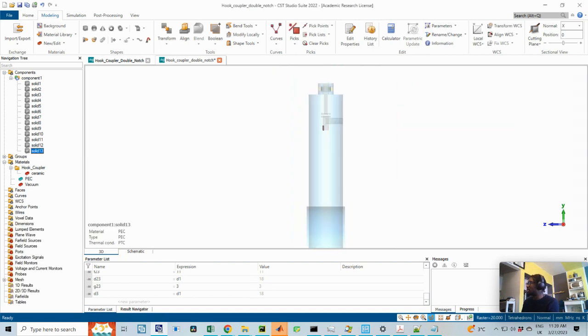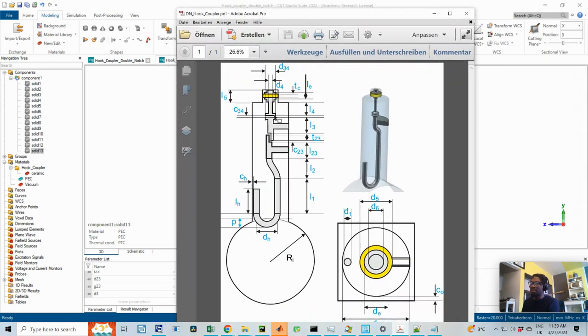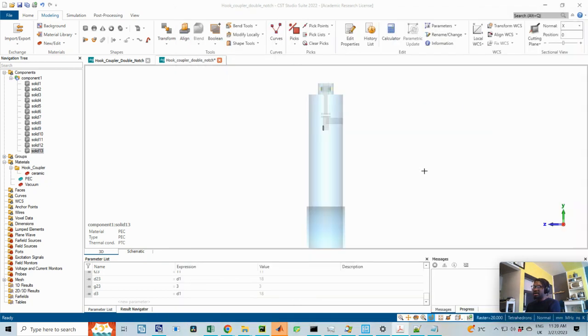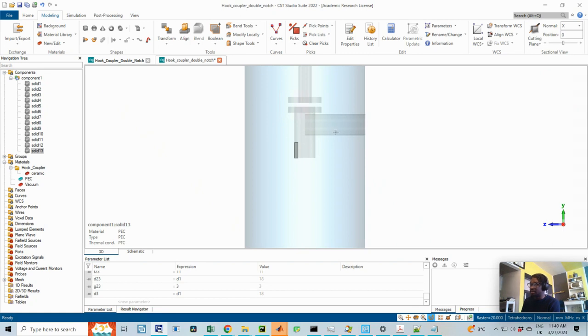Now the mistake I made is that, as you can see, I always make this mistake. The orientation is really important. The orientation of the coupler is really important. So the orientation is kind of facing this beam pipe. So the beam pipe Z axis, the XY plane of the beam pipe, that's what it's facing. But what I have here is that this is facing the YZ plane. So I need to change that. I have to change the orientation because the cylinders are symmetric anyway. I don't need to make modifications, so the only thing I need to modify is the direction that this is facing.